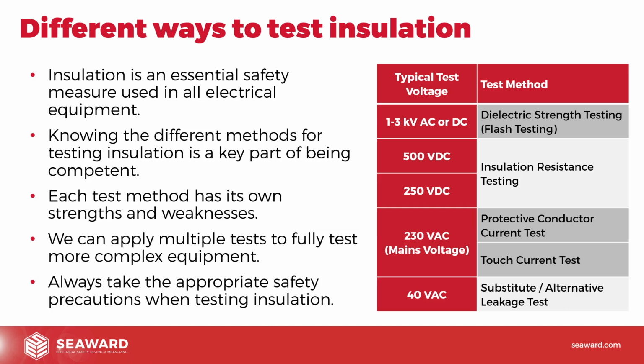Hopefully that's giving you an idea of the options on there. As I say, we're going to talk today about the bottom half of that table, and last week we talked about insulation resistance. But flash testing is there as an option, though the code of practice advises against that for in-service inspection and testing. But if you do feel that the risk warrants it, as I say, it is quite common in the tool hire sector, you can carry out those tests if you wanted to as well.